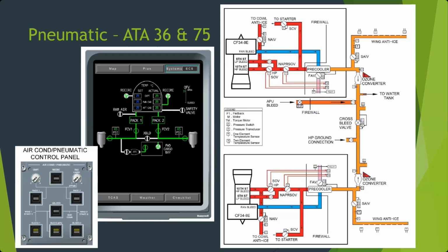You can see there's a couple other valves downstream, closer to the engine: high pressure shutoff valves and check valves. Those we often don't have direct control over. Those are more something that gets managed automatically. We'll look at what those are. But here we have our bleed air shutoff valves, 1 and 2, on the left and the right.